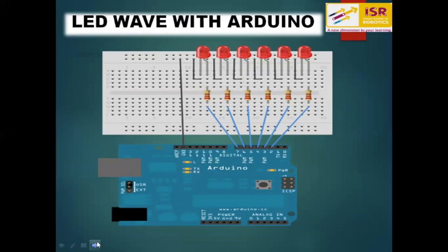Now we will learn how we can make LED wave circuit with our Arduino. So this is the circuit diagram in which we have used 6 LEDs along with 6 resistors, and all these LEDs and resistors, positive and negative, is connected to the Arduino board. Here what we have done in the circuit is the positive terminal of your LEDs, that is the anode, is connected to the resistor, and the second end of your resistor is connected to the Arduino board digital pins.